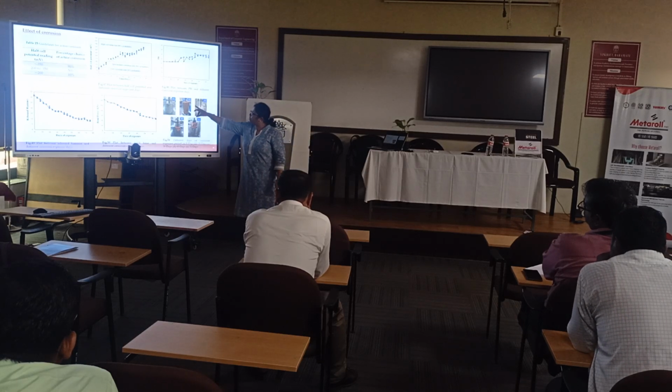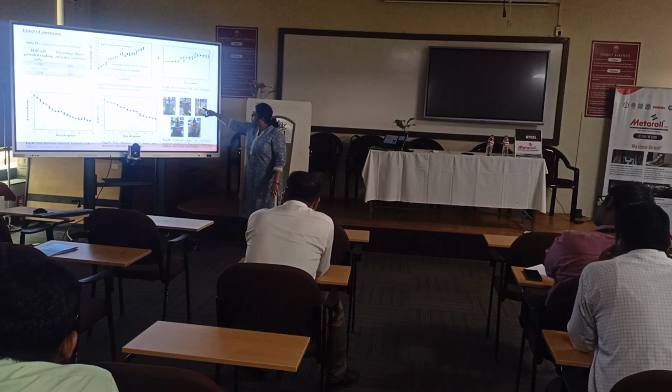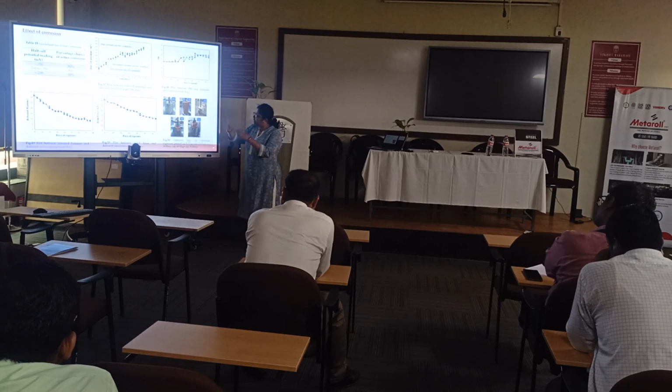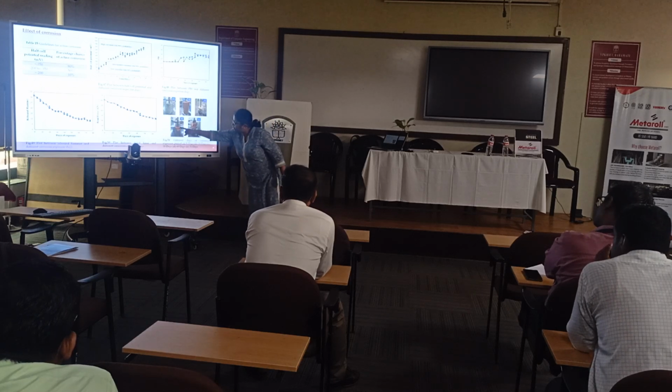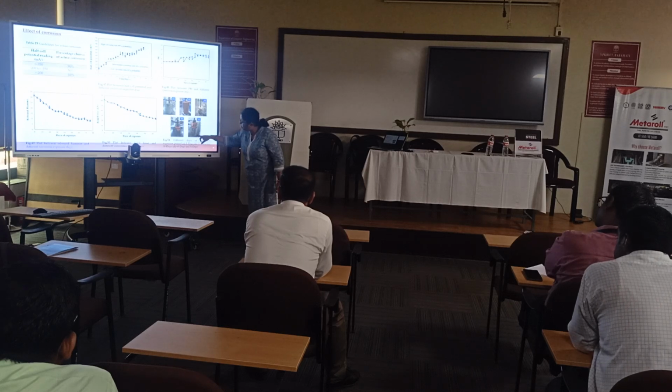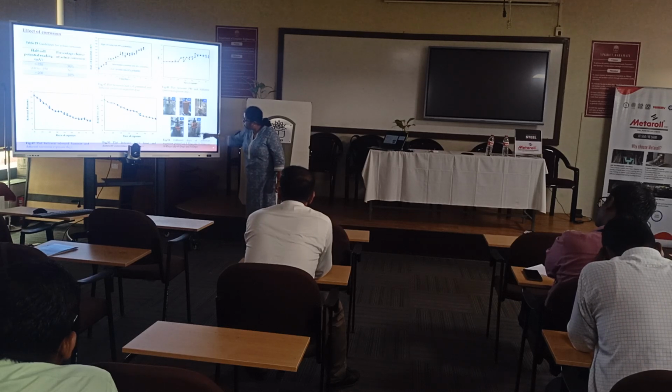So you see the rusting, discoloration. Rusting started initially at the surface joint between steel and concrete, then there is maximum deposition, then some cracks, and mostly the rust is completely deposited, and some of the cracks also transmitted from the top to bottom, and some concrete is spalling out at the bottom.